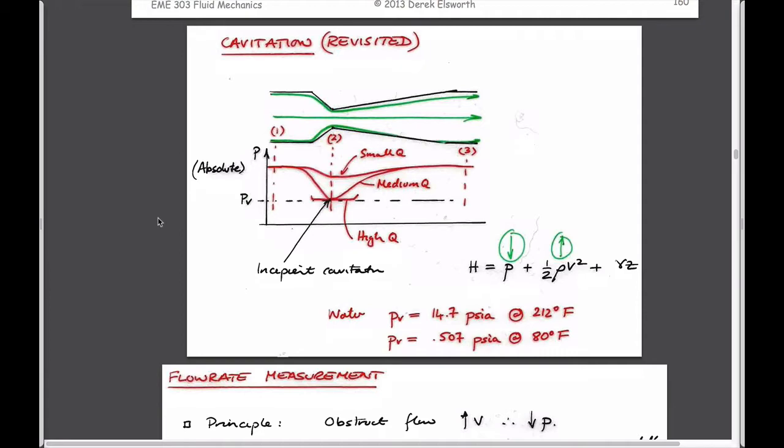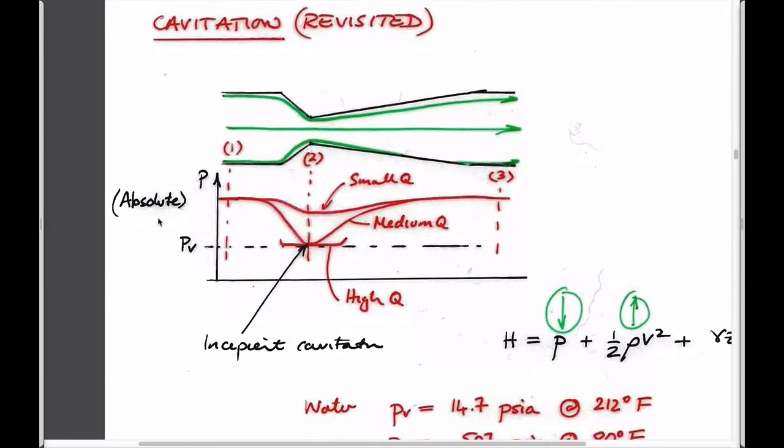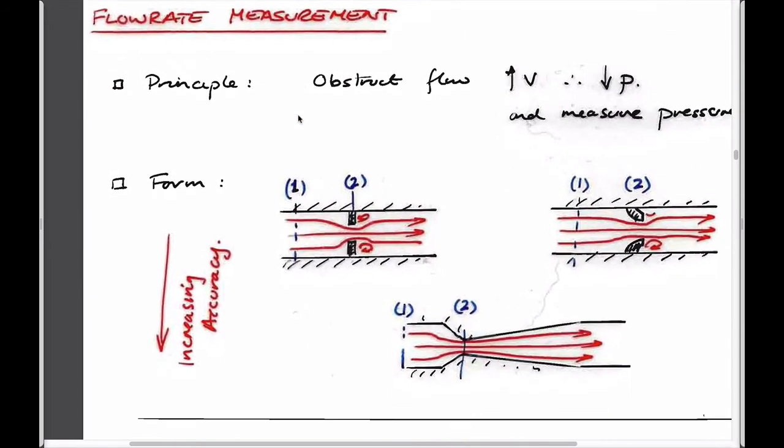Basically, this is the idea. So when we talk about Venturi meters, this is just what we saw. The Venturi meter in the diagram was initially an orifice plate, and so I'll come back to that. But so long as you can obstruct flow in some way, either with an orifice plate that partially constricts flow from this width to this width, then we know from what we understand about Bernoulli that things will speed up. And as it speeds up, there's always this trade-off between an increased velocity and a change in pressure, because it always has to be constant, those three terms.